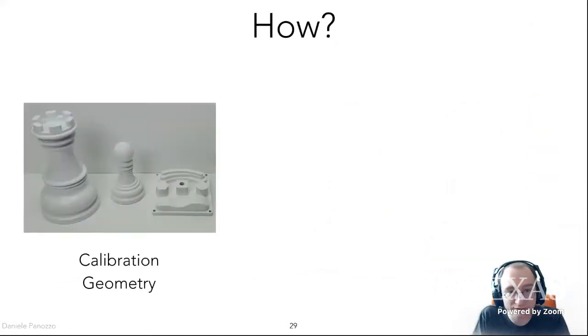So the ingredients here to make this scanner and simulator work is that we calibrated it using components that were CNC milled from aluminum with a very extremely strict tolerance, so that we already know the shape of the object at a resolution with errors that are way below 1 pixel of our camera, so that we can trust the geometry that we get from here. One of the major challenges in this project was to actually paint this object. It's surprisingly difficult to paint an object without changing its geometry and to get a uniform painting. And this is something that cost us an immense amount of time to do right.